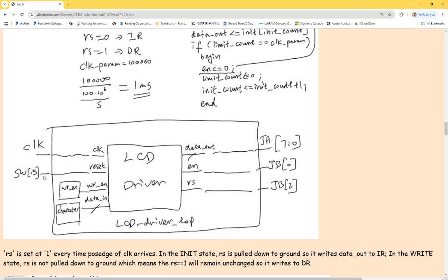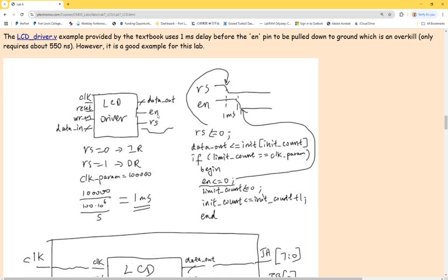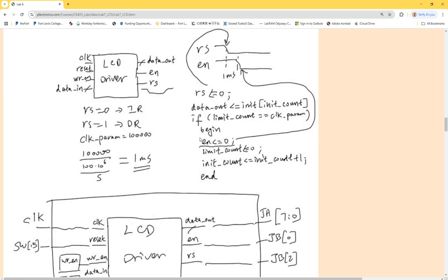So the switches can be used, but the switches are not real data. I'm not asking you to use these 8 switches to encode that ASCII code, right? We're not doing that. The switches are just switching between the characters. For example, if switch 0 is on, I'm sending this character to the output. If switch 1 is on, I'm sending another character to the ports. And the clock is always being used. It's a 100 megahertz clock, updating all the data, all the digital systems, all the ports, and everything in the system.